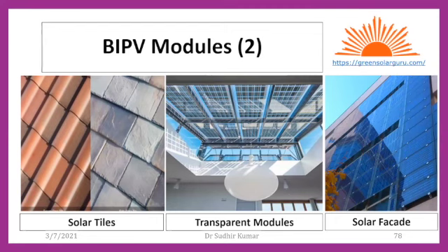I wanted to know, as a technical note, what will be the maximum mismatch in the wattage or mismatch in the voltage while paralleling two different modules or two different strings? See, straight away you cannot say, but I told you last time also. Suppose you have 300-watt modules in the series, and one of them is 280 watt. Then that whole series will give you 280 watt only. The whole string will become 280 watt.